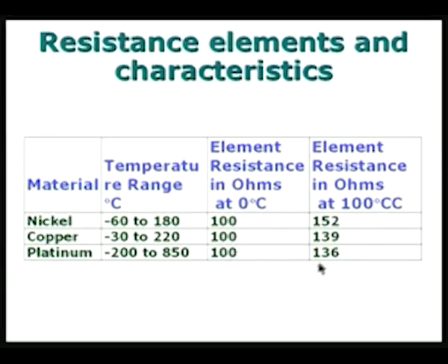The main difference between resistance thermometers and thermistors, which we will see later, is that this variation of resistance is very small in the case of resistance thermometers, and the resistance increases with temperature. In the case of thermistors, it is going to decrease with respect to temperature and also decrease by a larger fraction, and therefore, thermistors are more sensitive, but they have a smaller range compared to the resistance thermometers. The case being, we are talking mostly about the platinum resistance thermometer.